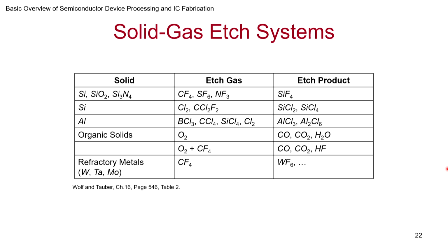Now, one of the things that is interesting about this plasma processing is you can monitor what is happening. How? It is a plasma, so at least a significant fraction of the atoms will be in an excited state. That means you know what atoms are present, because there will be optical transitions of the electrons. So by studying the optics, you can find out what is present in the chamber. So you can know whether the reaction has started. Have you finished etching all the films? Supposing you are etching tungsten, and you have etched all the tungsten films, then you will no longer find the signature of WF6, right?